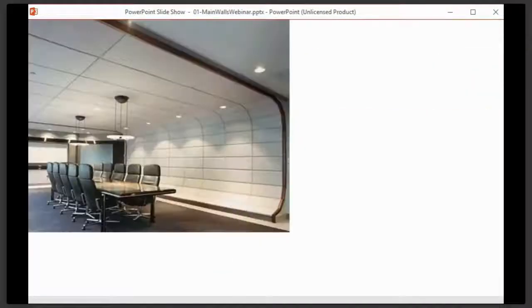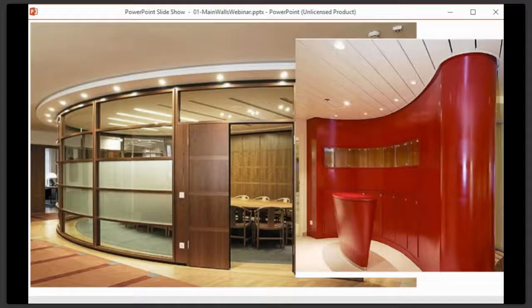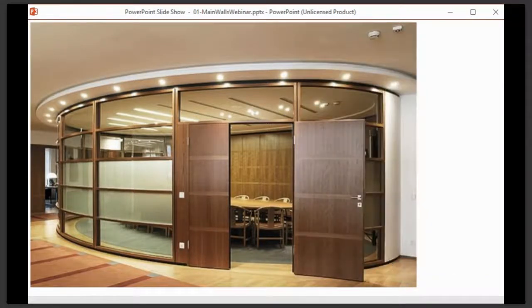because I didn't find images for these just because we didn't have enough time. Okay, I'll show you very, very quickly. This is a demountable partition here. How these are made, basically, you have a framework and you attach it to the ceiling, you attach it to the floor, and then basically you slot these partition panels into place. Generally this is one large prefabricated panel. It slots into place. The framework is usually like a track that's made to hold this firmly in place, and then once it's put into place, there's ways that you join the partitions, you seal them, etc.